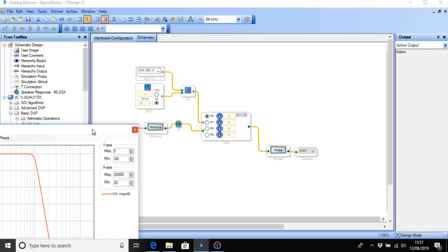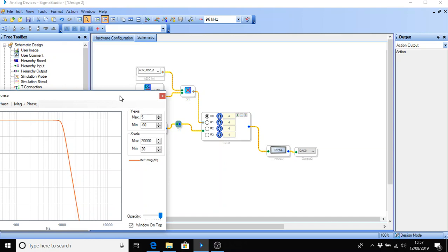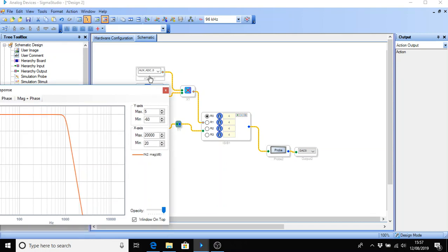All these are being driven from ADC0, which is one of the 4 potentiometers on the board, and I'm pretty sure I know which one it is. So what we'll do is link, compile and download this to the board, which has now been done. I'm going to turn my radio back on. Generate some noise. I need to plug the board into it. Okay. So if I now turn the potentiometer,